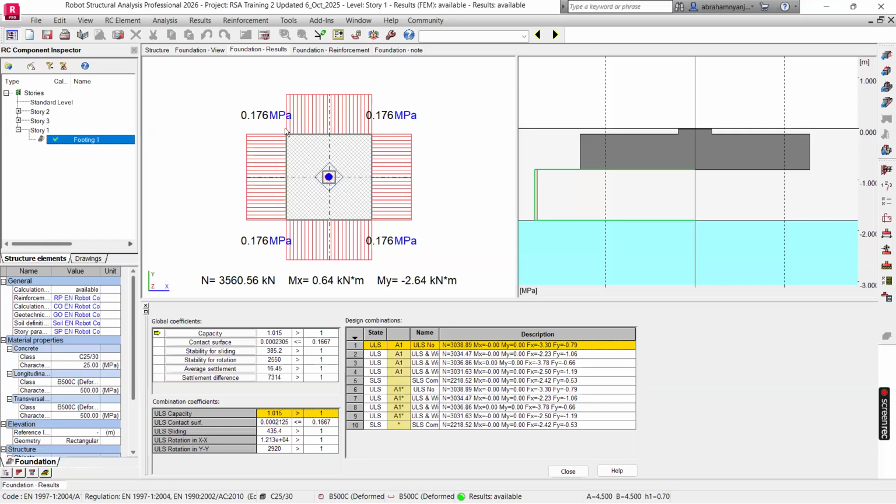because if you have more pressure on this side, then the soil on this other side will experience more stresses, more pressure compared to the soil on this other side. But good enough, it is way below the bearing capacity of the soil, so we don't expect the soil to deform. It will take the loads, so we don't need to worry about that.